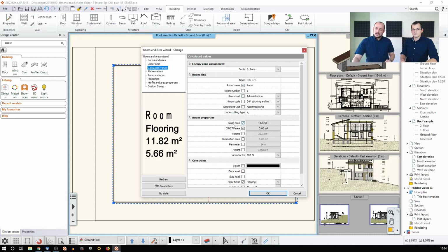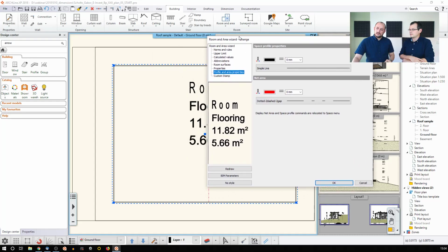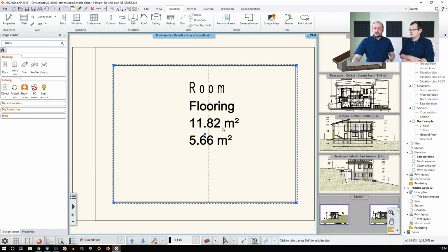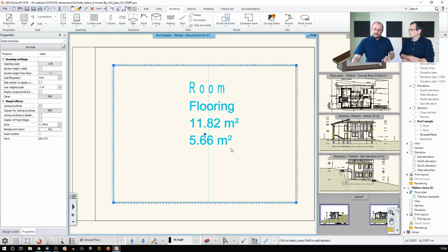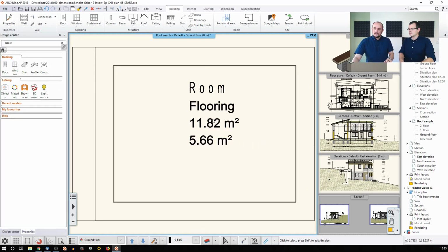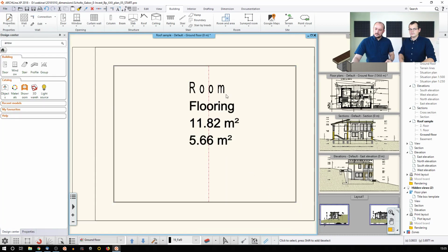First things first, I activated both of these, and then I went to the profile and area properties, and I made sure that it is represented red, with this dashed line, and then it turned this into a visible clue here. When I already placed it, I used this here. It's called the net area on/off switch. If I just disable it, I won't see it, even though it's there. But if I go back and say, okay, make it visible for me and enable it, then I can see it here. So that's how you can enable and disable it.